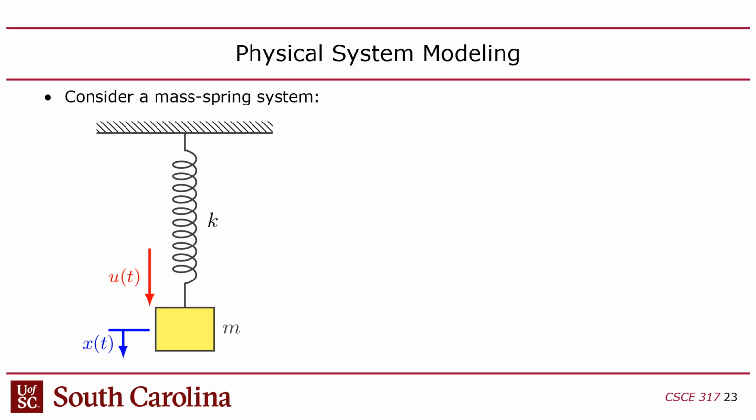So if this x becomes negative, like if I push up on the spring, what's the spring going to do? It's going to try to extend. It's going to put out an opposite force. Likewise, if I take this mass and pull it down and x is positive, the spring's going to want to contract. So the spring is either pushing out or contracting, depending on the sign of x, and the force that it has in doing that is determined by the stiffness K.